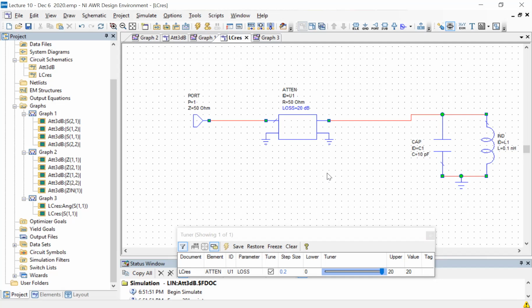I don't know which example you saw, but it's true that you can now connect the filter or that device directly on the network analyzer and just put a 50 ohm port on the other one, and then you can get S11 and similarly S22. Quite often, for various reasons, sometimes just practical, sometimes laziness, the network analyzer already has this long cable connected, so I don't want to remove it and redo it here. So I'll just look at it at the other end. But yeah, there are various reasons for that.